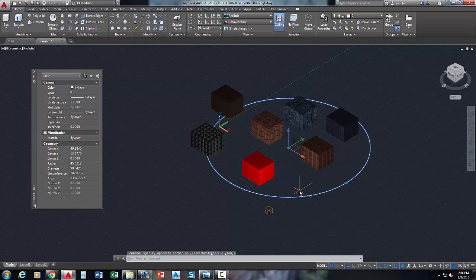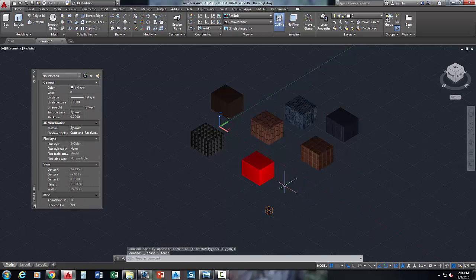Okay, so you could make a star shape of lines, and click, whatever you want to do. Just put them all on there and they'll still be on the same plane. As long as your lines are all on the same plane, then you can move your objects and snap them to those lines and delete those lines out or turn off that layer, and then those are all on the same plane. And that's going to help you a lot, because you don't realize it.